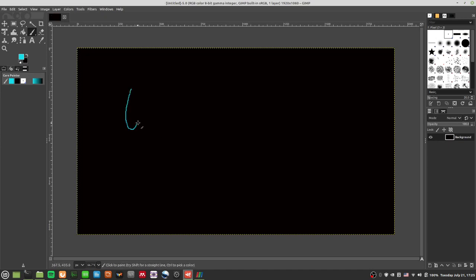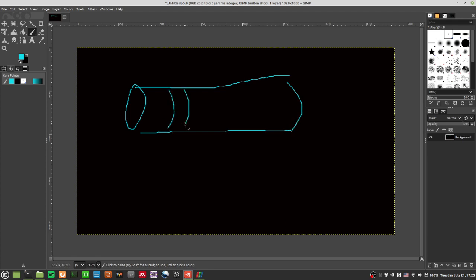When you have a pipe and you have all these mesh values, what this will do is calculate the wall shear stress, or tau wall, at every single mesh point. So let's say this is tau wall 1, tau wall 2, etc. And of course these meshes will always have different areas to them.